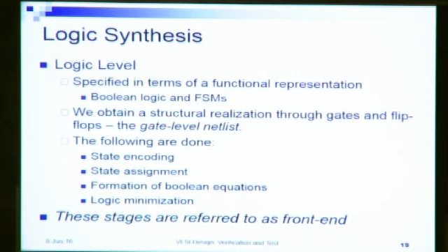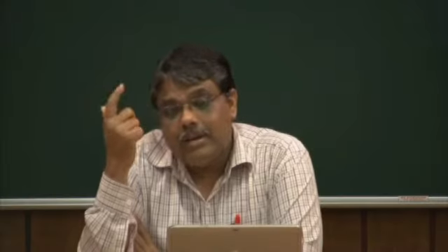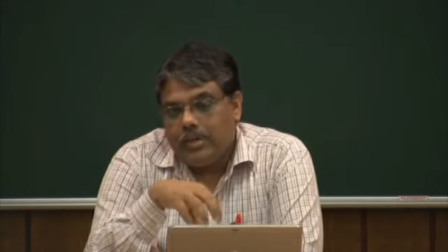So at the end of the front end of the logic synthesis step, we have a minimized digital circuit corresponding to the functionality that we had at the beginning of our architectural synthesis step. That functionality was transformed into a set of Boolean equations, and those Boolean equations were then realized in terms of gates at the end of the front end of the logic synthesis step.